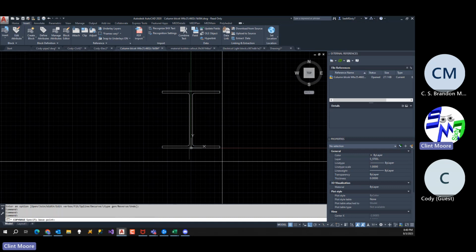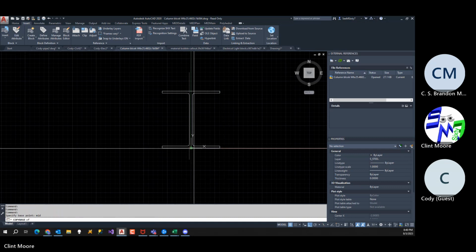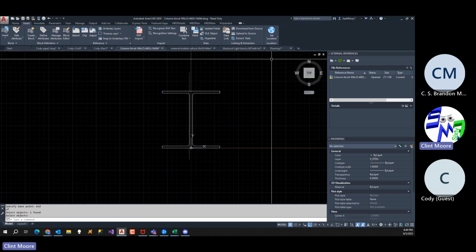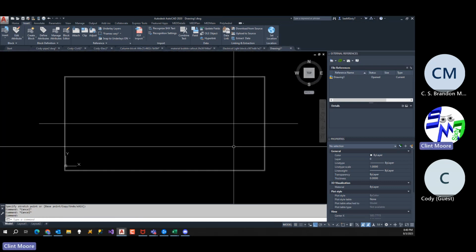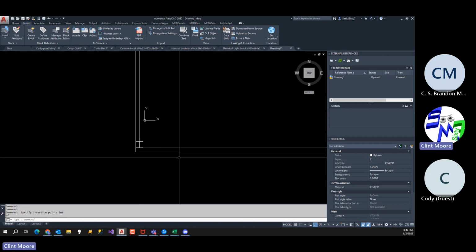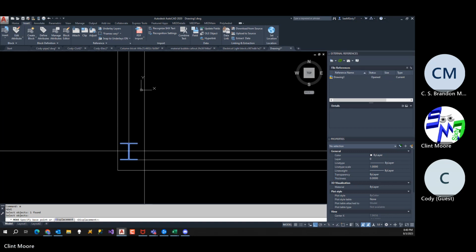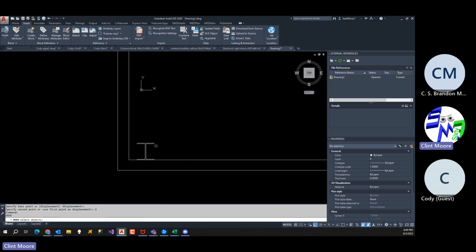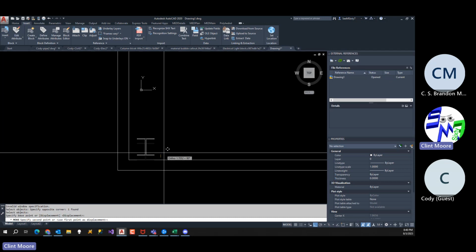All right, now Control-Shift-C from mid of that. Boom. Now I've got the whole thing. I'm going to place that over here in my drawing. Okay, Control-V. And I'm going to place that at the intersection of that there. I'm going to move this over here 6 inches. Boom. I'm going to move it away from the wall 6 inches.